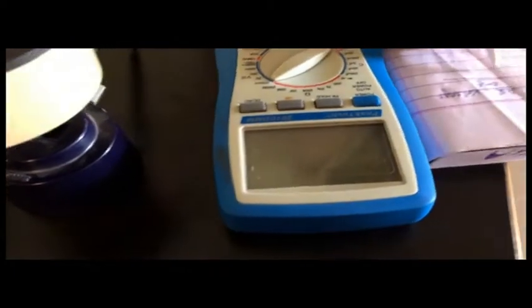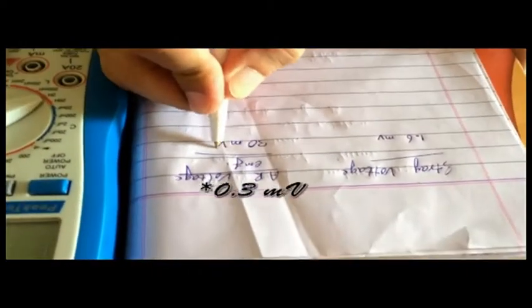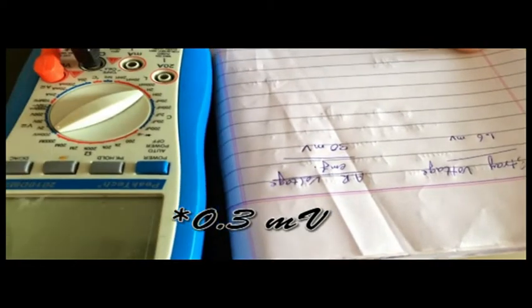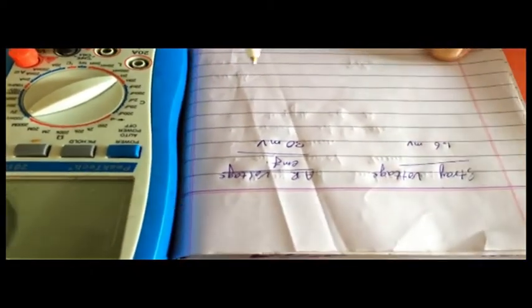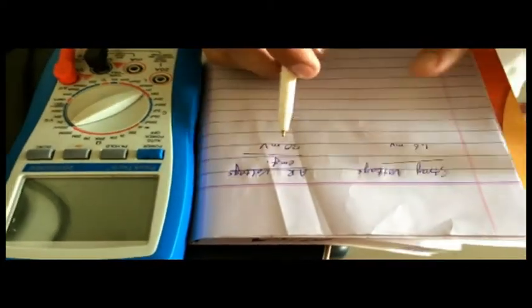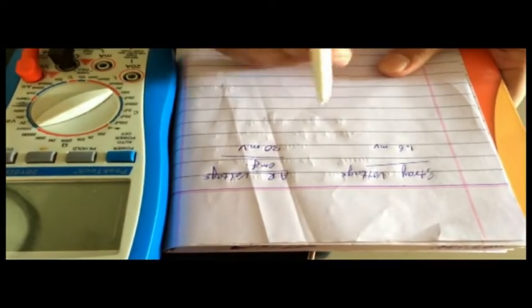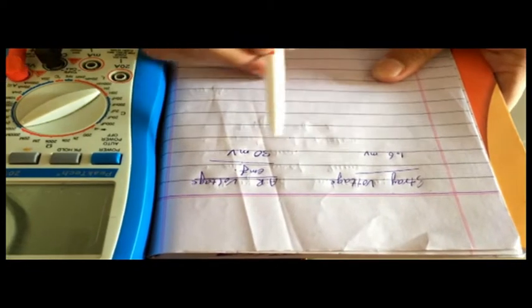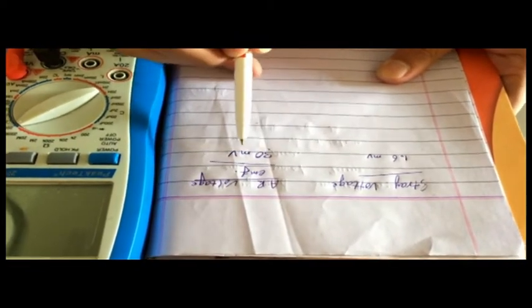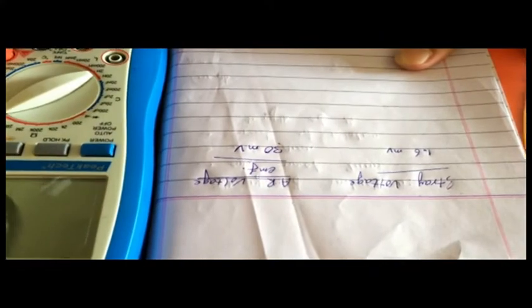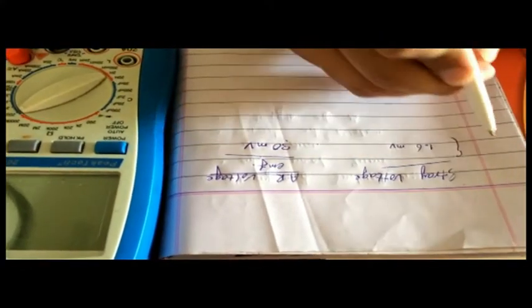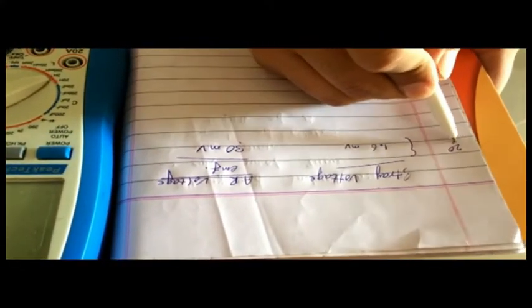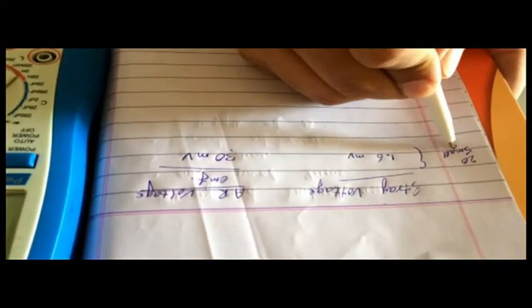As you can see, we got 30 millivolts while rotating our unit. I shall explain later why this voltage is not stabilized at a point, and why it varies so many times within a second. But first, we see that we have 30 millivolts of maximum voltage from this coil. And here I explain that this coil has 20 turns and a small area.